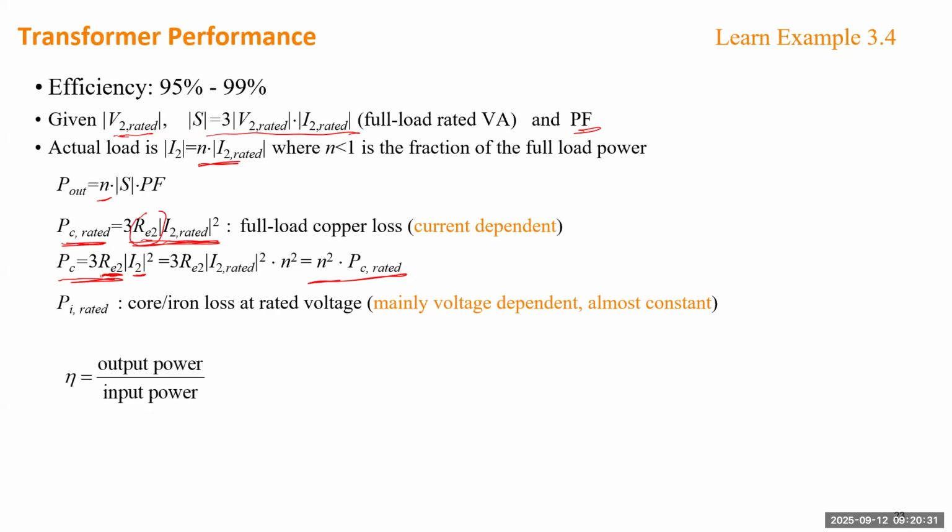Even if there's some room to use the transformer to control voltage, as we discussed in the later slides, usually the voltage can vary in a very narrow range. So it has to be close to the rated voltage levels. But current can change largely from maybe 0 to a fully loaded current. So the iron loss doesn't change a lot. It will be roughly the same value.